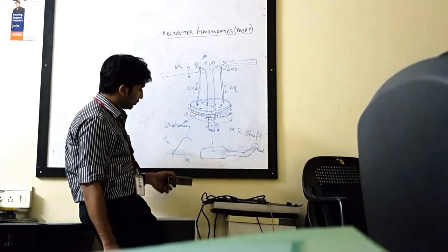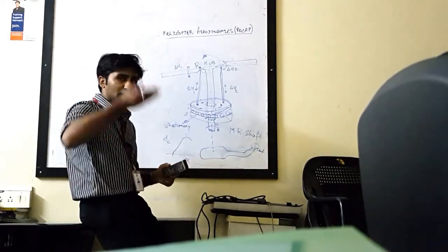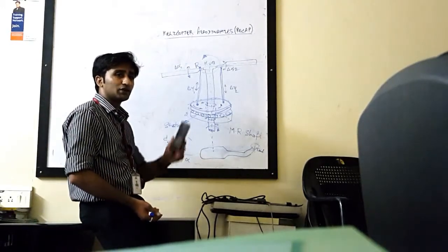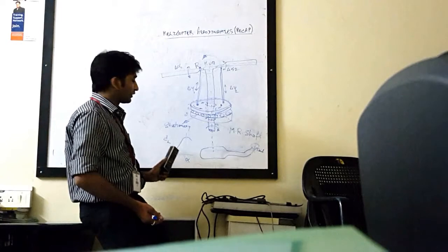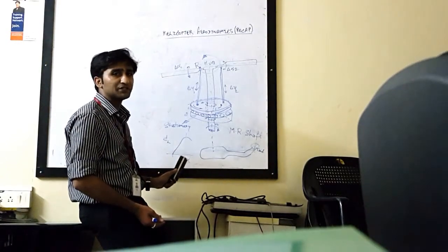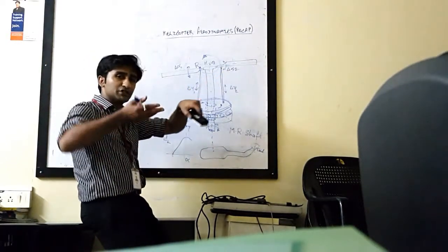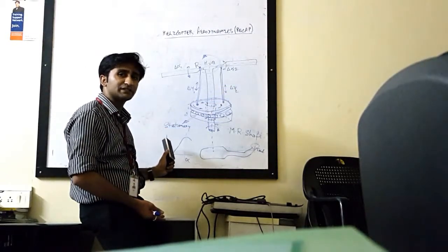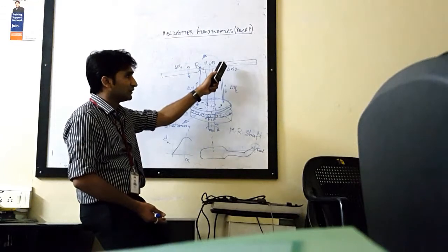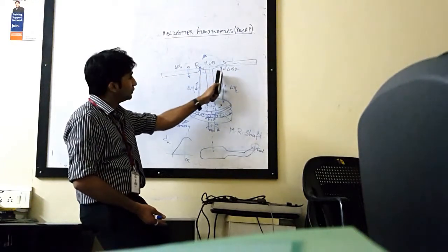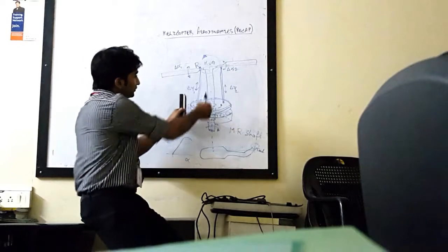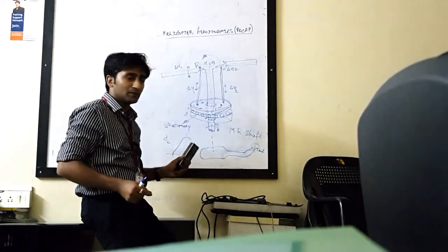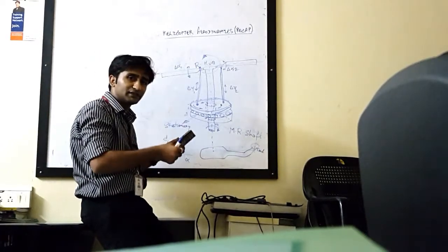So you know that during vertical climb, you need higher and higher lift in order to achieve vertical climb. So what you need to do is change the blade pitch angles. Each of the blades needs to rotate about its feathering axis by a certain alpha to achieve the required CL. So how that is done is you move both the control rods simultaneously by the same amount.